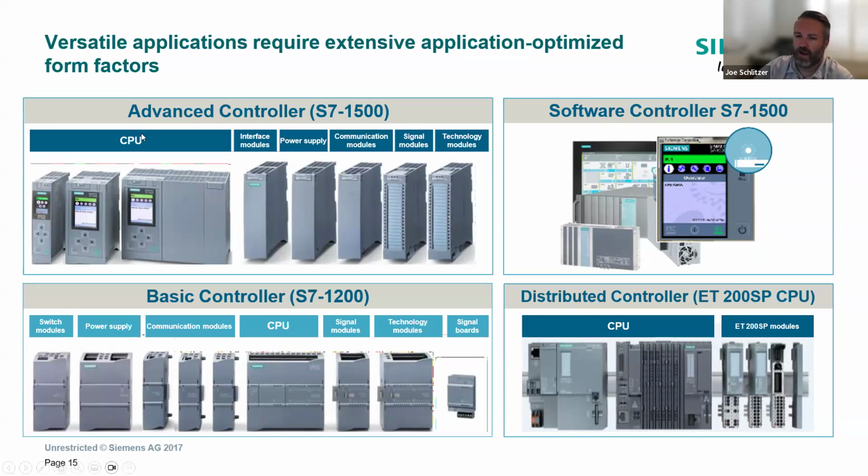So moving on up, we have our S7 1500. That's considered our advanced controller. The scope ranges from standard and fail-safe CPUs for small to medium-sized requirements. It does offer a compact size with integrated inputs and outputs, and supplemented with technological functions, all the way up to our most demanding high-performance applications such as motion control and high availability applications. The S7 1518 may be one of the fastest PLCs on the market today.